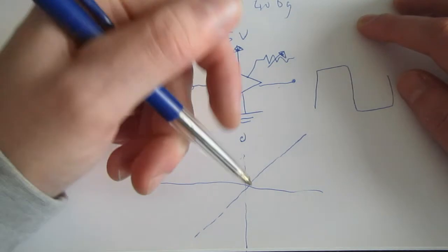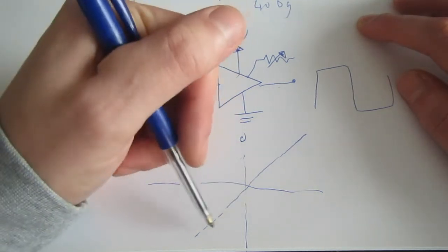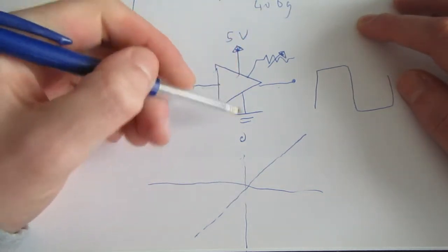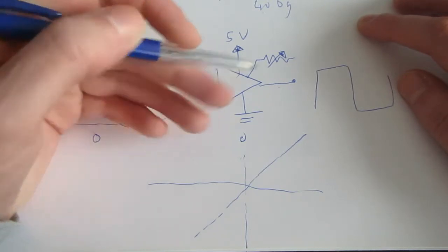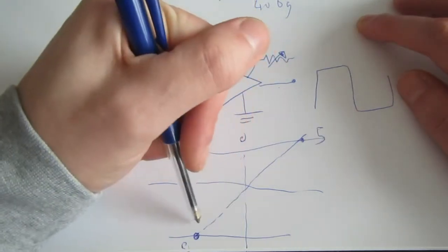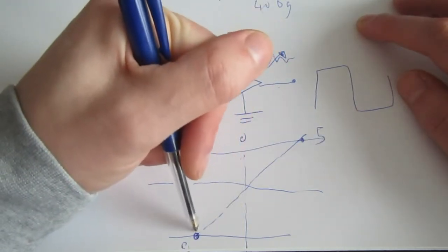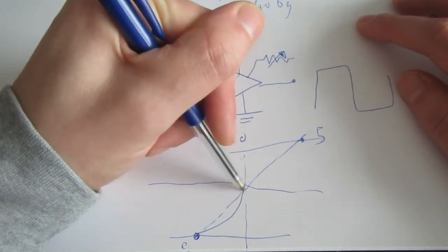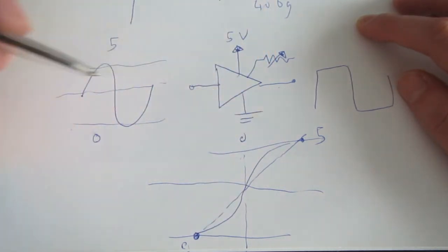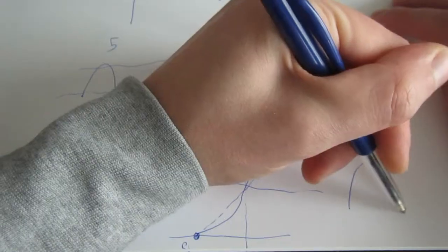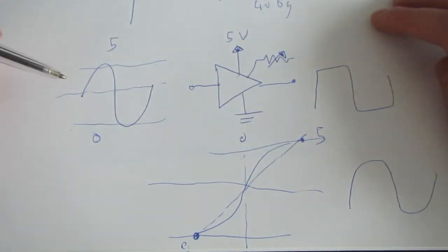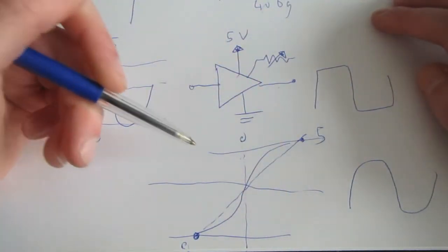Now, when I raise the gain, this line will become increasingly skewed because our amplifier is limited between 0 and 5 volt. Now I increase the gain, it will start getting skewed. And our sine wave will get a bit more square wavy.